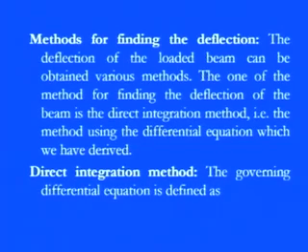That is the method using the differential equations we derived previously for the slope, the bending moment, the shear force and the rate of loading. If we apply integration, we can get all those values straight away. The first method, a very common and standard one, is the direct integration method using those governing equations.